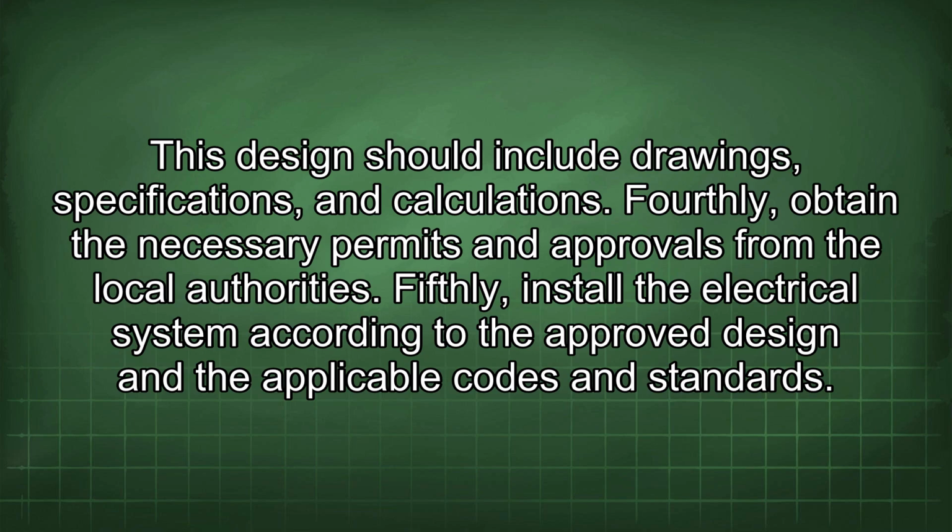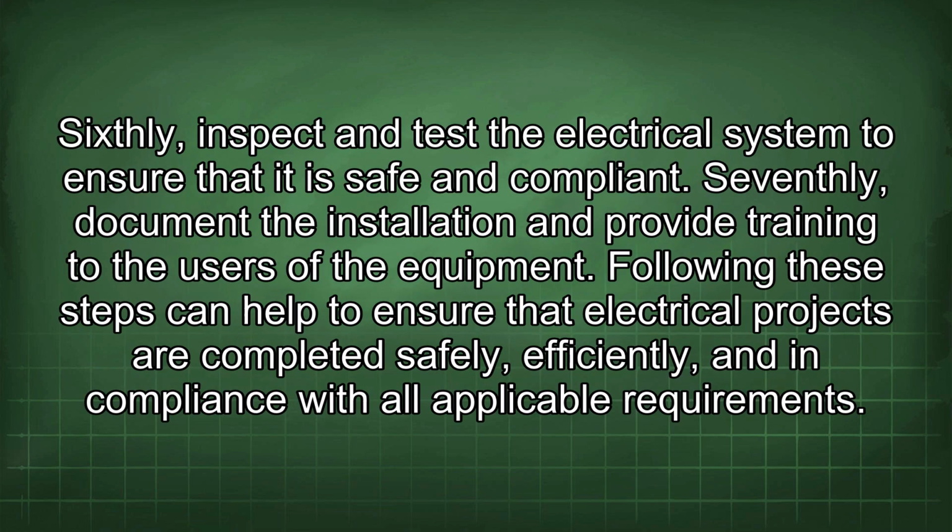Fourthly, obtain the necessary permits and approvals from the local authorities. Fifthly, install the electrical system according to the approved design and the applicable codes and standards. Sixthly, inspect and test the electrical system to ensure that it is safe and compliant. Seventhly, document the installation and provide training to the users of the equipment. Following these steps can help to ensure that electrical projects are completed safely, efficiently, and in compliance with all applicable